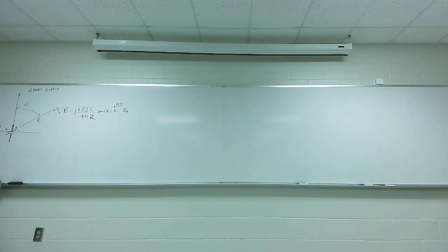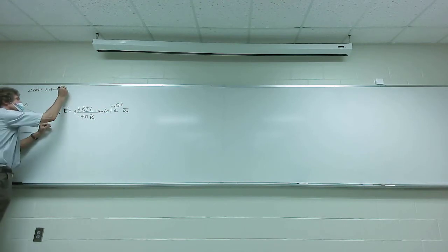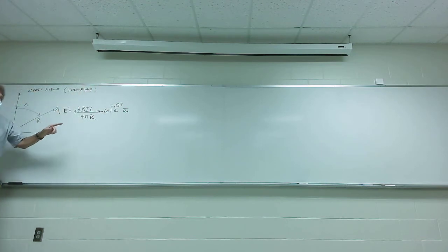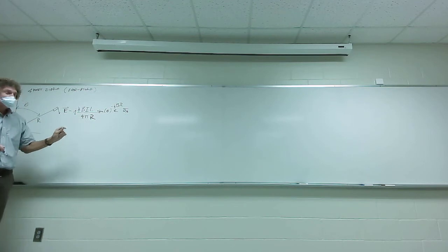Now, the things to get from this for the electric field, and this is in the far field, by the way, is that it varies as the sine of this angle, which means the electric field straight up and straight down at theta equals 0, or theta equals pi, 180 degrees, is 0. Y'all follow me? And the thing you take from that, dipole antennas never radiate up and down their axis. They have a maximum radiation pattern perpendicular to their axis. Do y'all follow me? Now, it varies as 1 over r, and it's proportional to I. That's basically what you gleaned from this.